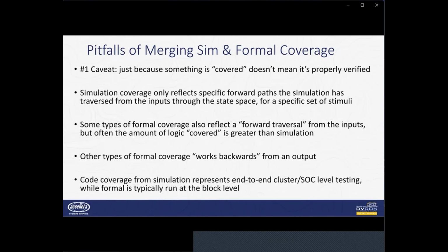Finally, regarding code coverage, the code coverage from simulation usually represents end-to-end cluster or SoC level testing, while formal code coverage is typically run at the block level. With that, let me turn the floor back over to Mark to show you some specific examples to illustrate these issues.